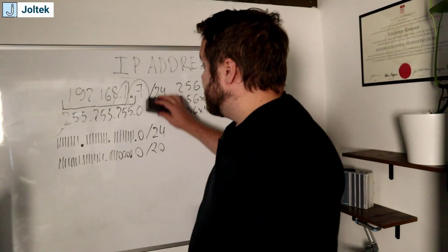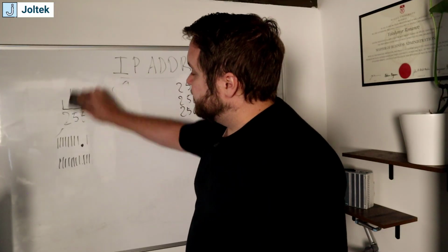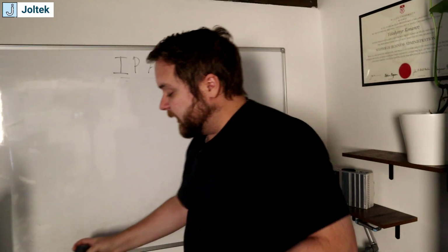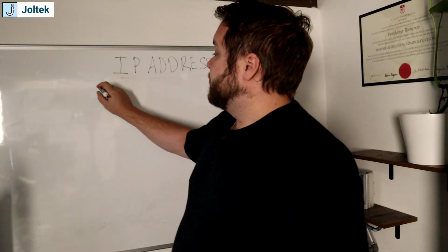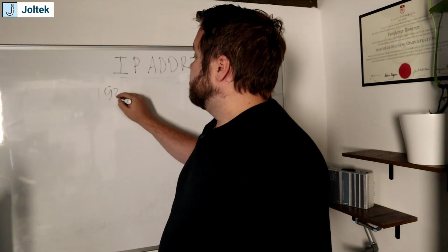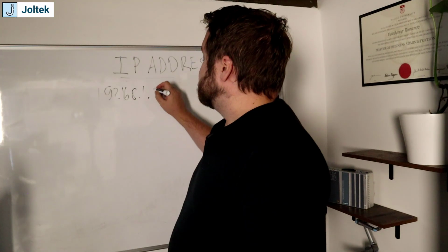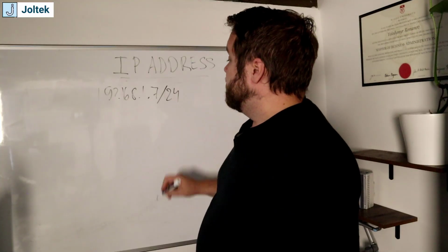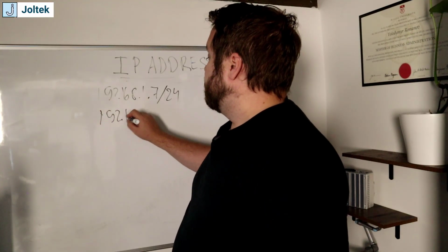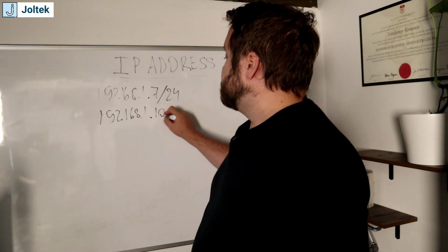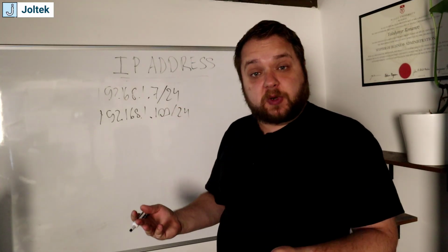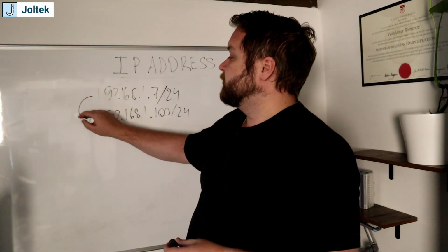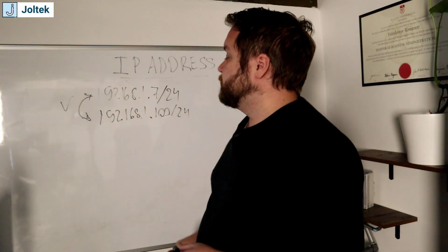And so let's look at some practical examples. If you set your IP addresses just as we did in the lab a couple of lectures ago, what is going to happen? 192.168.1.7 was the VFD, and this was, remember, /24. So if we set the laptop to 192.168.1.100/24, that is perfect. As we've seen in the demonstration, we were able to ping both of those devices. So this is perfectly acceptable. This is going to communicate.